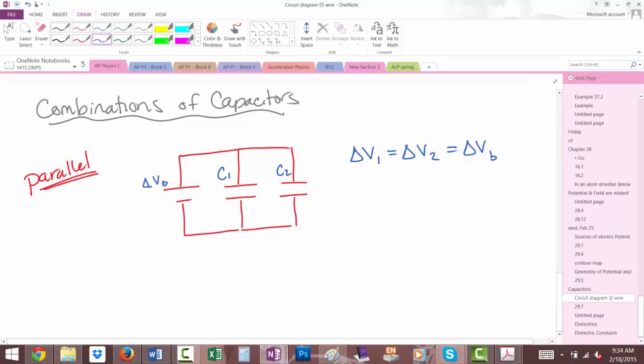You have to watch out here because AJ's played this game before, so I don't want you to just rely on him. I want to make sure it makes sense in your head as well. The total amount of charge stored here is going to be bigger than if there was just one on there, right? Does that make sense? Okay? The charge here plus the charge here. So the total amount of charge, I'm going to call that Q total, is going to be equal to Q1 plus Q2. The amount of positive charge on one, the negative charge on the other. So it's not like adding up the positive charge and the negative charge absolute values. It's the total amount of charge that's separated.